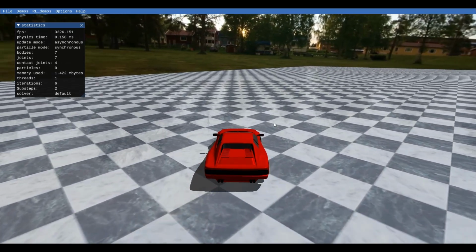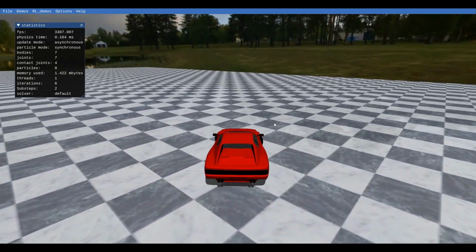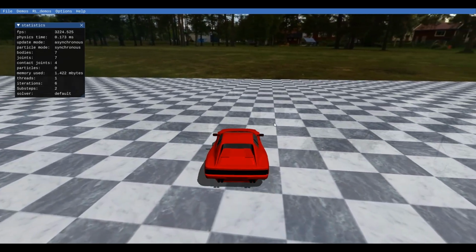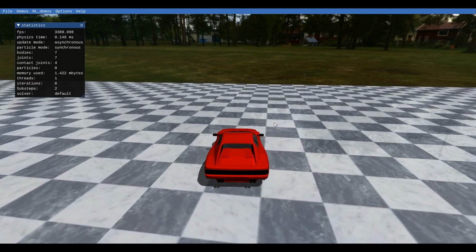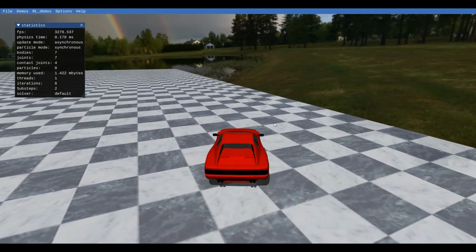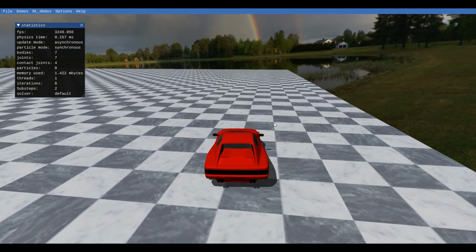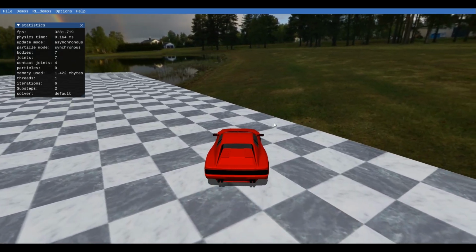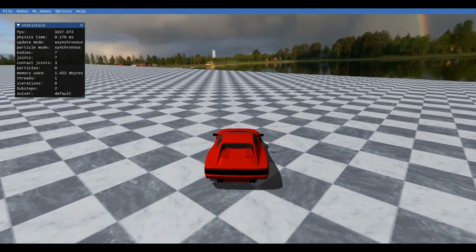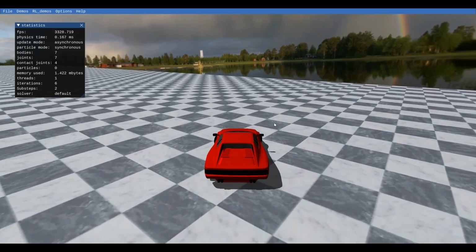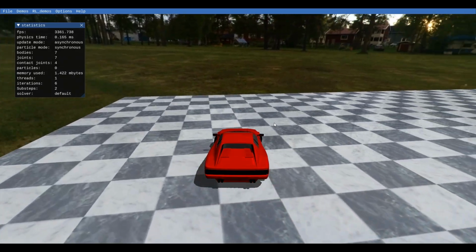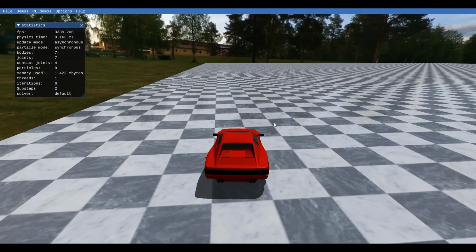The simulation itself is not incorrect. It is simply behaving the way an assembly of rigid bodies would under the classical Coulomb friction model. There are several ways to make the simulation behave more like a real motor vehicle. A common approach is to make the car front-wheel drive or all-wheel drive. Other techniques involve using the classical bicycle model to calculate the vehicle side slip angle and yaw rate, then apply auxiliary torque to limit excessive sliding.